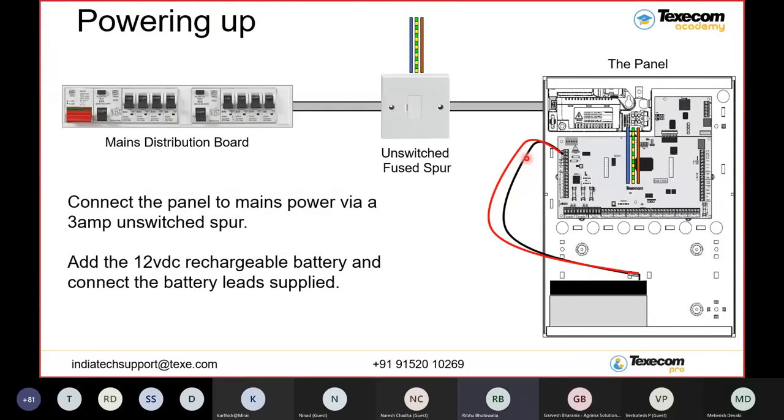So gas leak sensors, as such, till date, in Texecom we don't have gas leak sensors, but yes, you can use the smoke detectors. Texecom has smoke detectors available, or you can also use third-party smoke detectors like System Sensors or Apollo. That is also possible. Yes, you can use it. No problem. And one important thing to keep in mind about smoke sensors in residences, do not keep them in the kitchen because Indian cooking style typically gives out a lot of smoke.